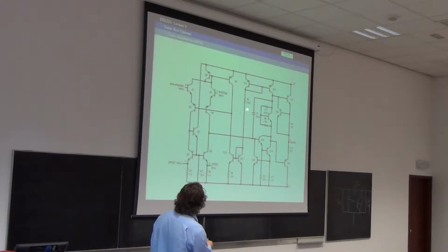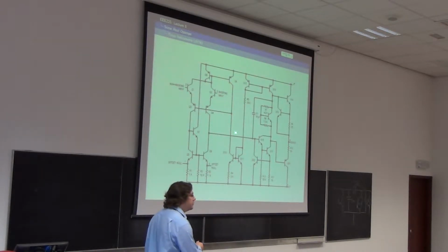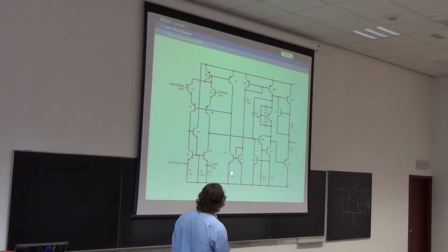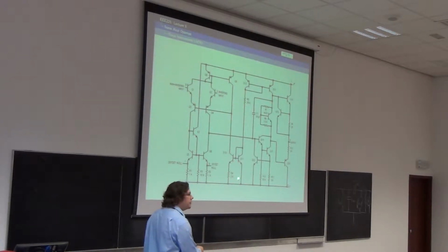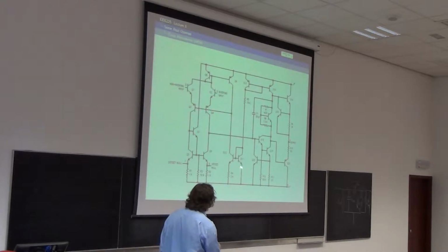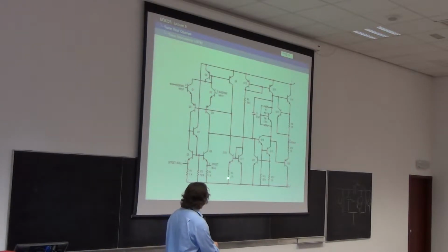So that gives us a current in this leg, and that gets mirrored to this leg, except there's a ratio of the currents that are mirrored because of this resistance popped in to say hello. 0.7 across there, somewhat less than 0.7 across here, because the current flows in R4, and that develops a voltage across R4, and that voltage across R4 must be taken away from the 0.7.